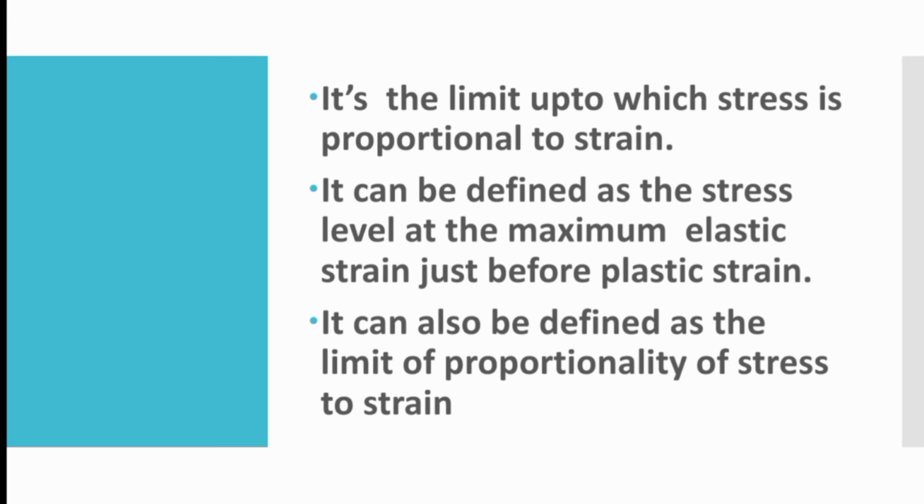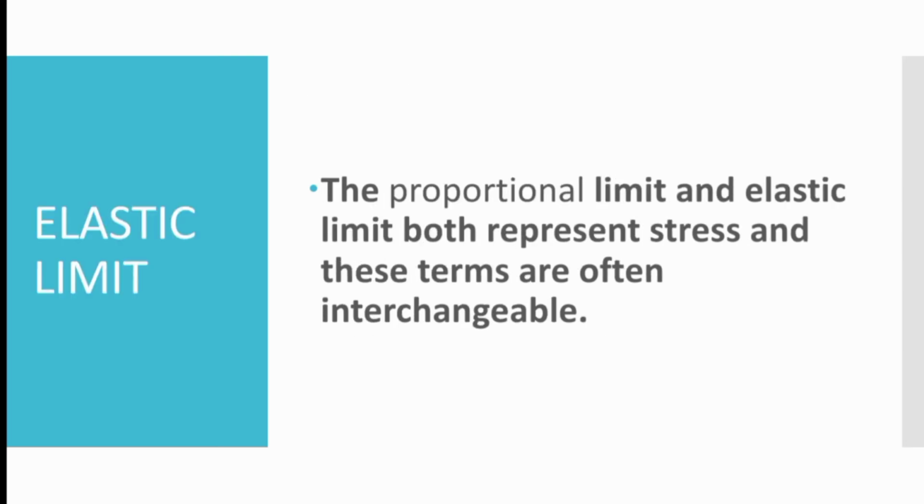It can be defined as the stress level at the maximum elastic strain just before plastic strain. It can also be defined as the limit of proportionality of stress to strain. Hope you all understand what is proportional limit. Moving to the next topic, that is elastic limit.